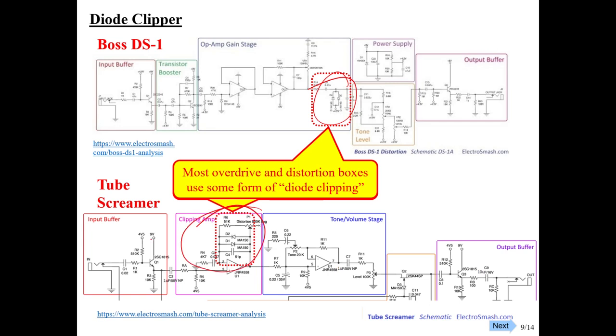But again, common emitter, so input buffer, output buffer. We've got a little bit of gain here with some tone control, a volume control, and then don't worry about this FET. That's just a switch to turn the signal flow on or off. So when it's operating, you can just view this as a straight through wire that's connecting there. So that's the idea.